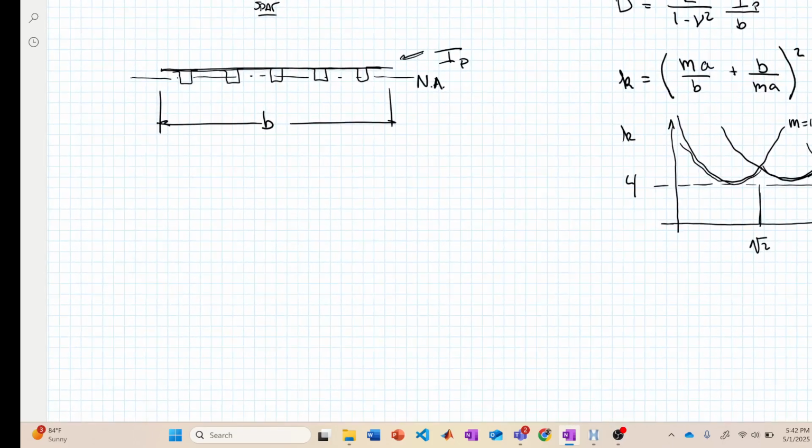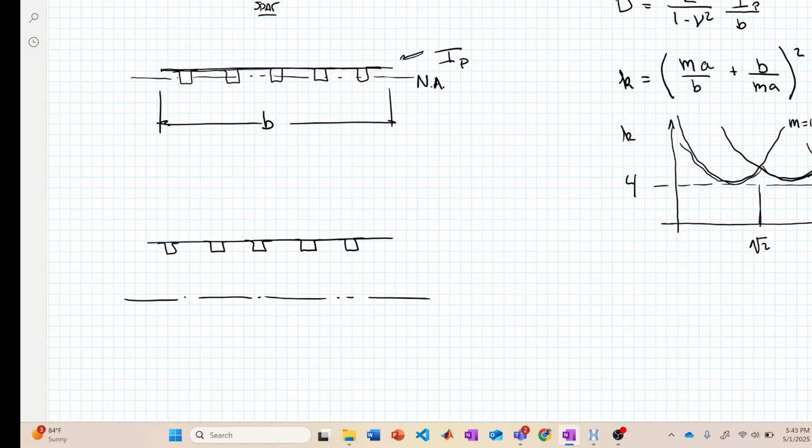Now, to figure out what's the actual load in that system, much like with the stringer, now we have to think about this in the context of the entire wing system because we want to find out how much axial force is picked up by the rest of the structure versus this system here.